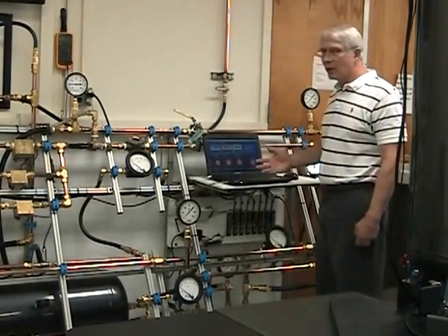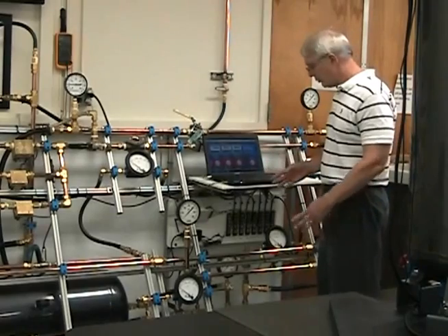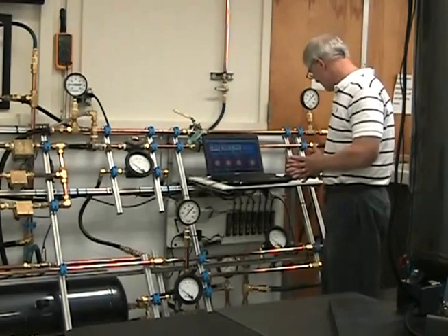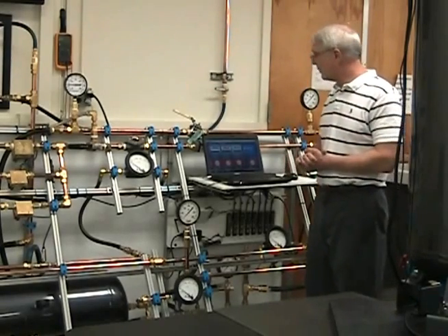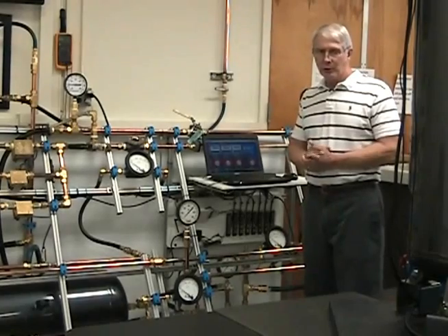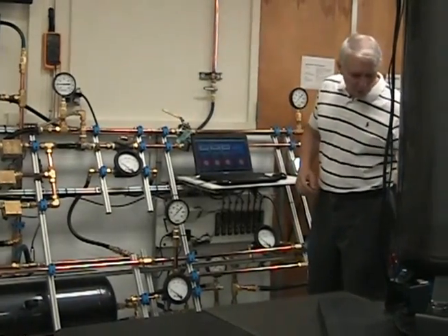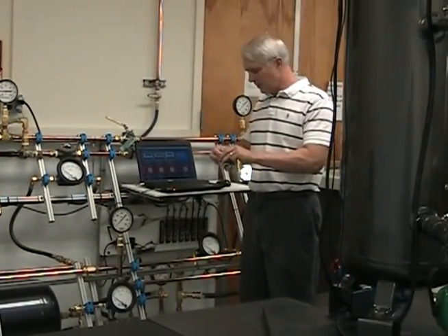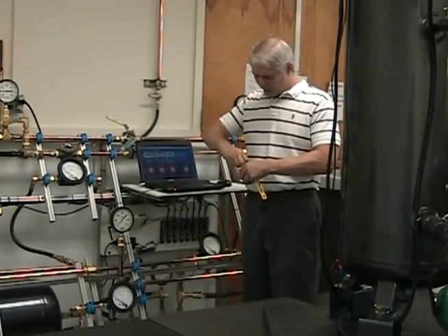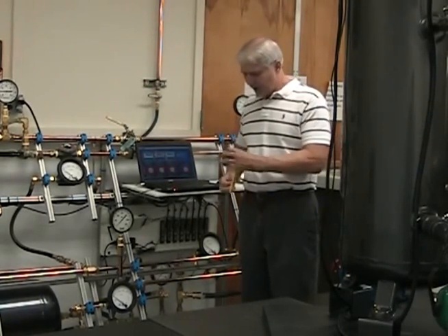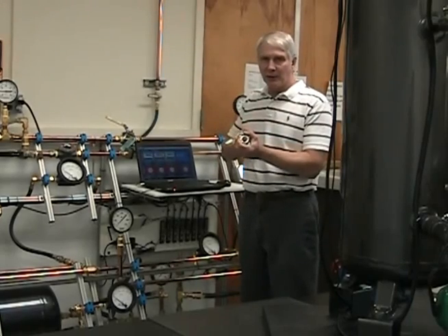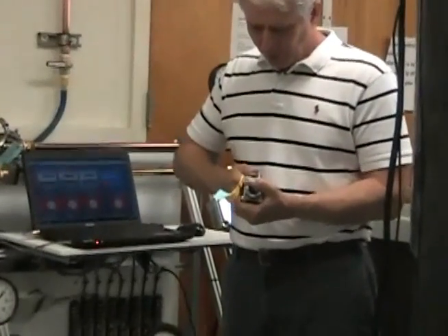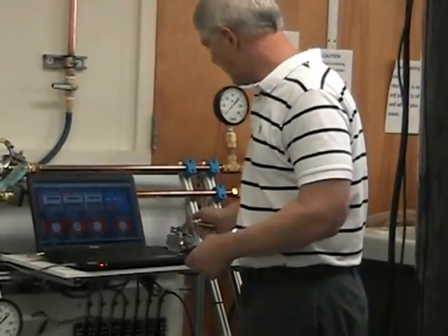So then you do it for your different runs, whatever settings you have. You'll do it for the big pipe, the small pipe, the elbow, and I think that might be it, but whatever it says in the lab write-up. I also have an extra control valve right here, and I want you to look inside of it. This one's a little bit smaller than that one, but it's the same geometry. So let me take these out. You look inside, and you can see it's a ball valve, but it has a special geometry to it. So sit here and open and close it so you can see how it operates. I'll have it sitting right up here in the area.